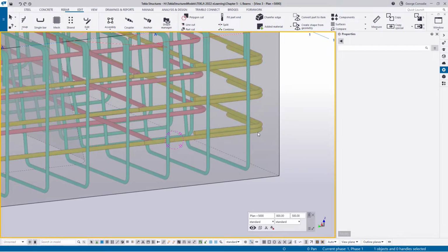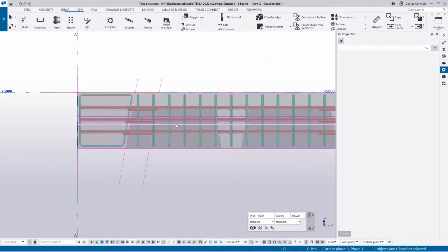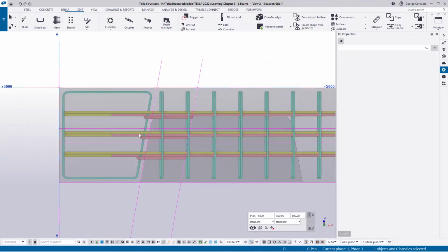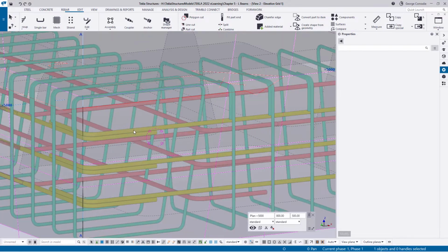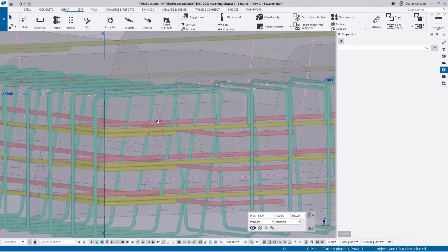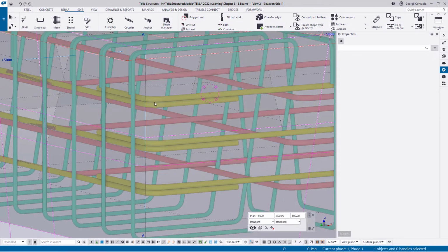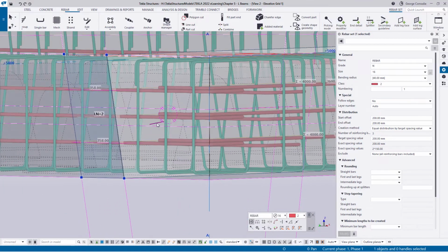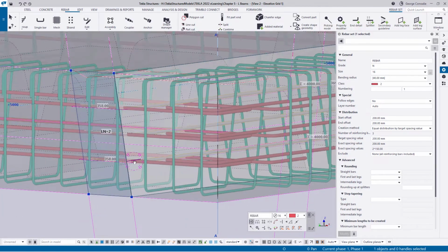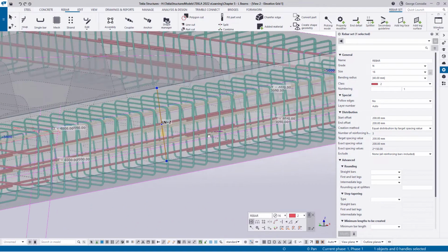okay, let's do this. If I go to this view, this is from grid 1 from the other side. I'll just go into 3D again. We can see the problem is this bar here is clashing with this leg here. So we can either use these bars or the inner bar. The inner bar is probably going to be easier to manipulate in this case. Let me just see what this side looks like. So these sides are 100% clashing there, and on the other side